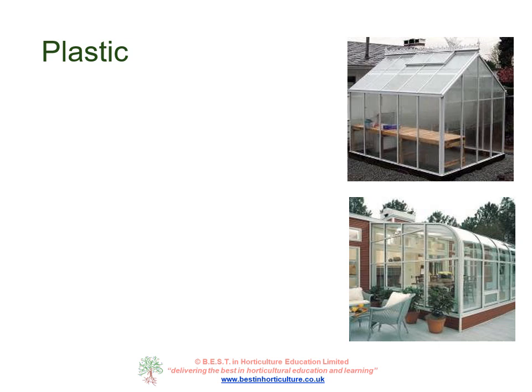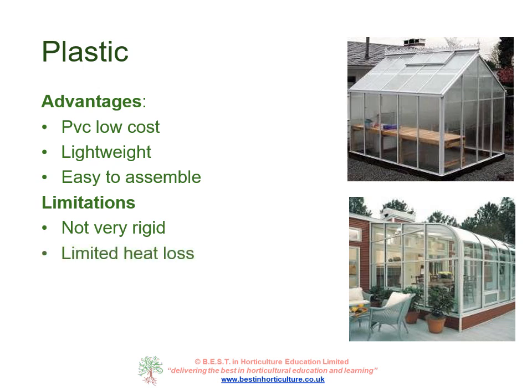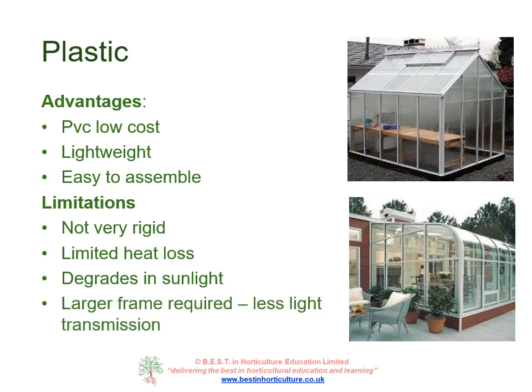Plastic is also used for conservatories and for domestic greenhouses. An advantage here is PVC is fairly low cost compared to other materials. It's also very lightweight and easy to assemble, but on the other hand, tends not to be very rigid, has limited heat retention, and will degrade in sunlight, particularly ultraviolet light. A larger frame may be required because of the strength issues, so again, less light transmission.